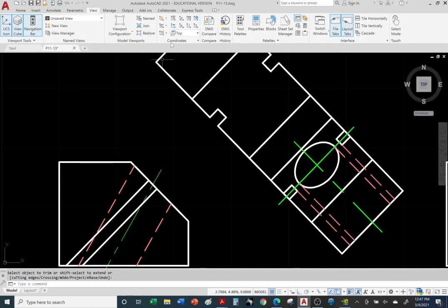All right, did you blink? Rewind the video and play it again. All right, so here we go. Here's our UCS, User Coordinate System. It's the plain looking icon out of all of them. Okay, so here we go. I'm going to click on UCS. So it's asking me, hey, where do you want to place your origin? Hey, I want the origin to be here at the corner of my bottom left corner of my auxiliary view. Click. Okay, so notice there's my new origin.